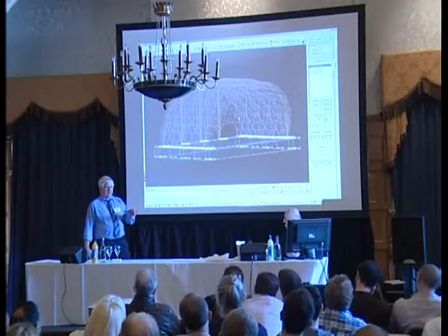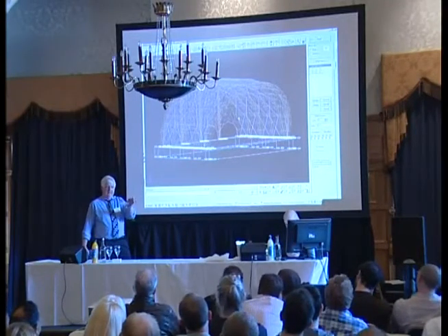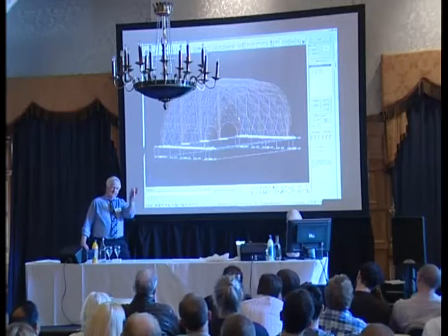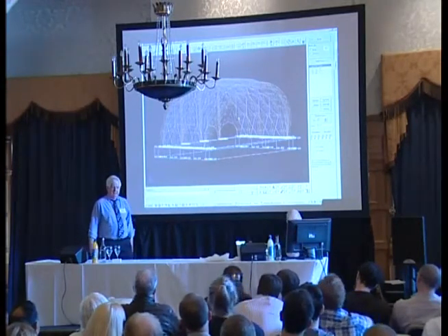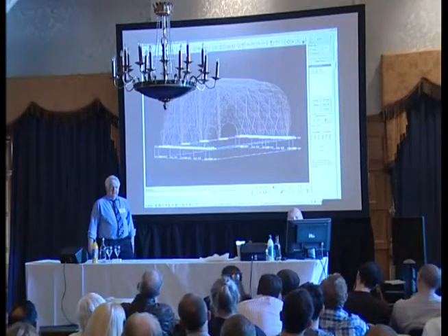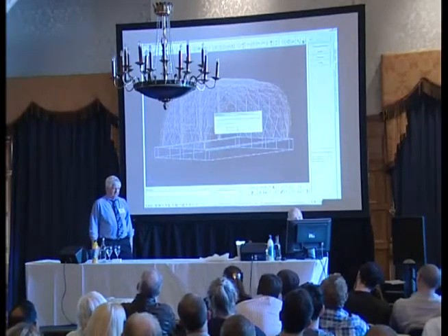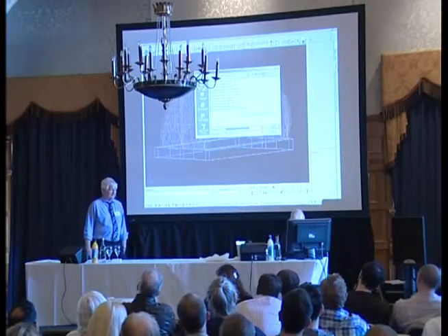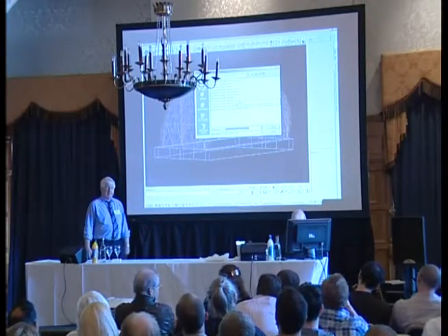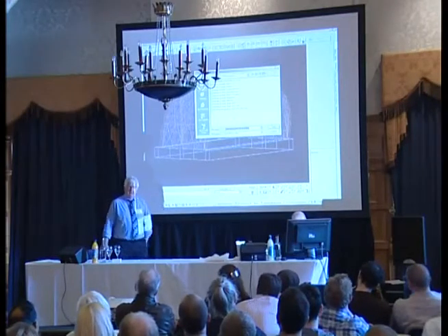It does do stress ranging. It will do stress ranging if you give it all the different load cases, with different positions. It will give you the stress ranging, which you can use for fatigue analysis. I don't think it does harmonics. I'll ask him if it does, but I don't think so. It'd be a good thing to do because he likes the challenge.